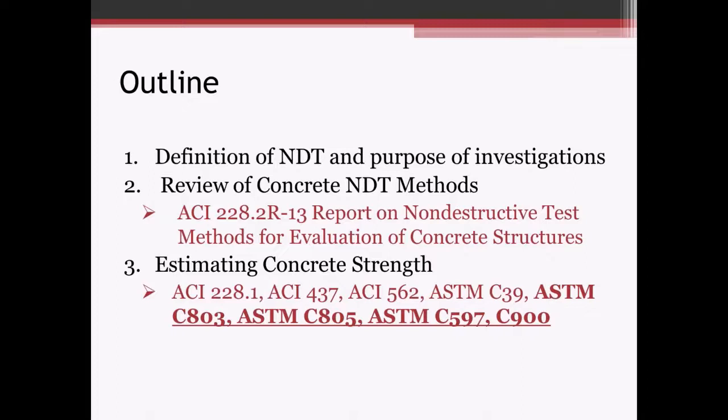You can continue dropping your geophone down, and if you continue to get reflections beyond 4 feet, maybe at 4 feet that's a pile cap, and maybe those reflections below the pile cap are a pile. But that's one of those situations where it could be inconclusive, and I've never performed that test, but I've seen the data, and I'm very familiar with seismic data, having worked in the seismic industry. That kind of data can be very tricky to evaluate.